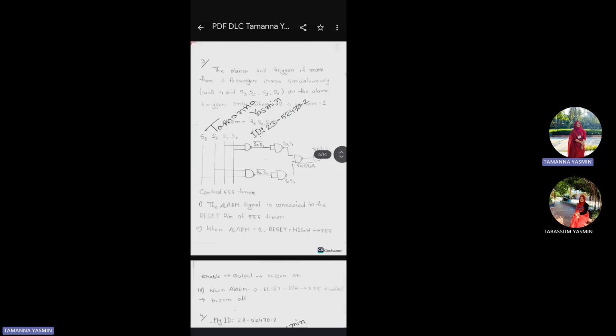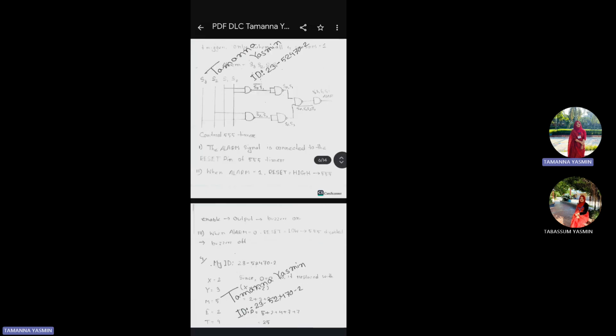To create an AND function from NANDs, you simply invert the output of a NAND gate. So I designed a circuit where the four sensor signals are fed into a single four-input NAND gate. The output of the gate is then fed into both inputs of a second NAND gate, which acts as the inverter. The final output gives us our alarm signal, which is high only when all four inputs are high.